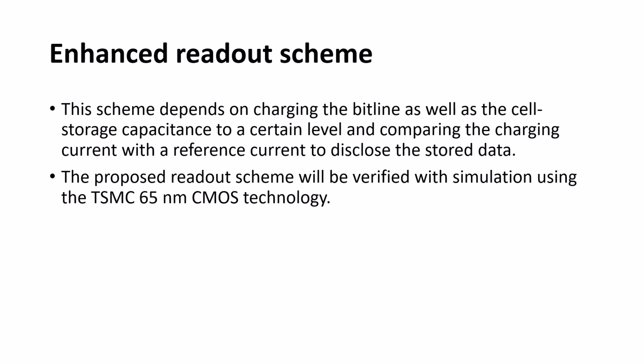This is simply due to the initial precharge of CS in case of one storage compared to the initial discharge of CS in case of zero storage. We will explain how this is happening in the next slide, where we have the schematic, and potentially we will dive into these simulations in the TSMC 65 nanometer CMOS technology node.